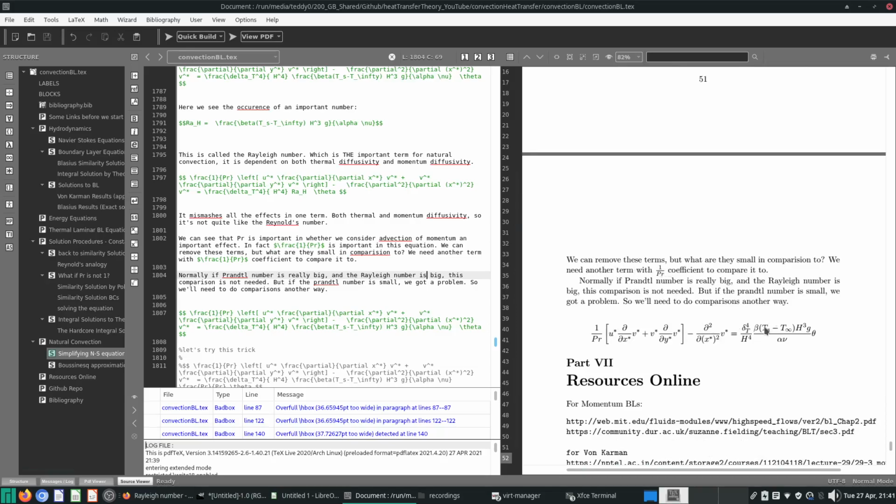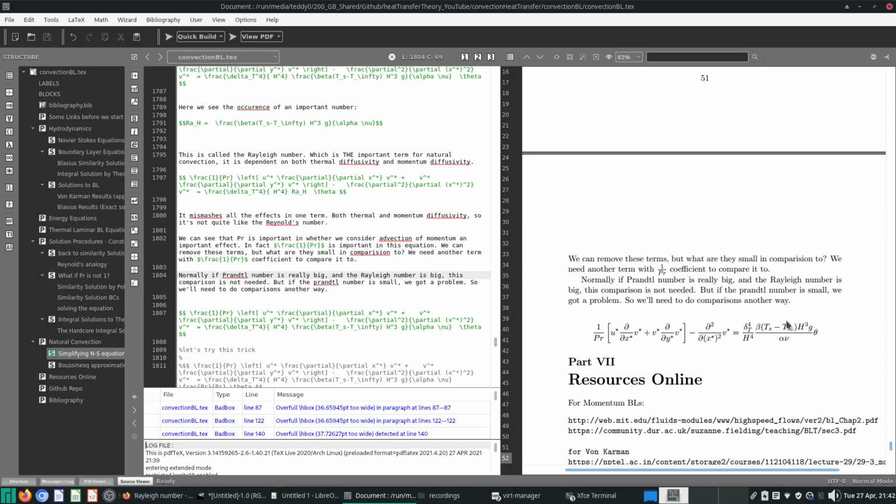So yes, one thing you will note from this equation: if your Prandtl number is very big, and of course your Rayleigh number is big enough, these two terms you never neglect, you find that these two advection terms will just disappear for fluids with very large Prandtl numbers. Which means that for thermal diffusion, within the thermal boundary layer, these two terms can just be neglected.